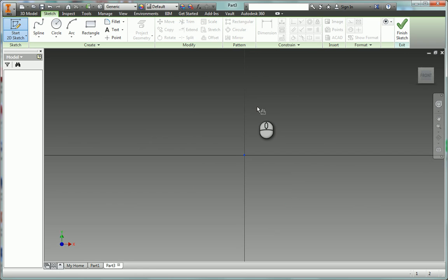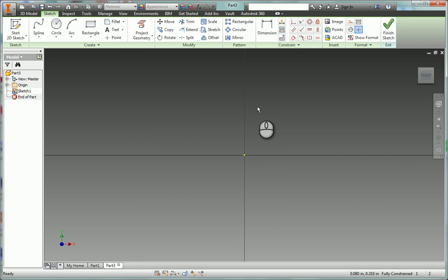We're going to start a new sketch. You'll see that dimension D0 is the overall plate depth, and it's going to be set at 3 inches. There's no equation for that. That's what it's going to be set at. D1 is the overall plate width, and that's going to be a 5:3 ratio with the overall plate depth. So we're going to take D0 times 5/3 to get our dimension, which will of course be 5 inches. To begin with, we're just going to put 5 inches in, and then change that in the parameters table.